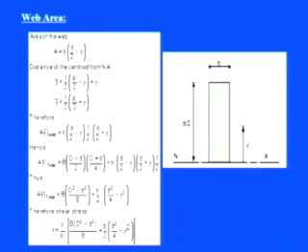So b into d by 2 minus y is the area, and then we have half of d by 2 plus y as the y bar. Now if we keep those things together, we have A y bar for this web portion. If you want to calculate for the entire region, meaning one web and two flanges, A y bar total equals b, first for the flanges, b into D minus d by 2, D plus d by 2, plus the web portion which we calculated, small b into d by 2 plus y, into half of the portion.